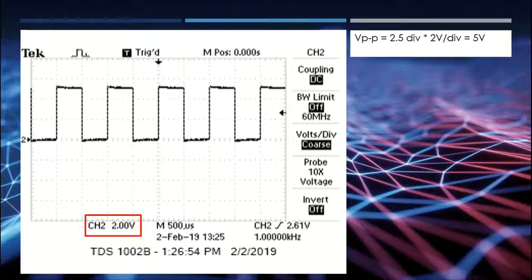So again, when you're looking at a signal and it doesn't make sense in terms of what you should be getting, a good way to check what you should be getting, of course, is to start with the reference. Then look at what caused that. In my case, it's because channel 2 is set at a probe of 10x voltage. This is what caused the issue.